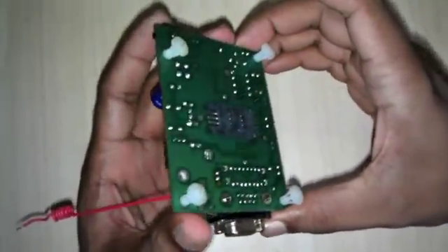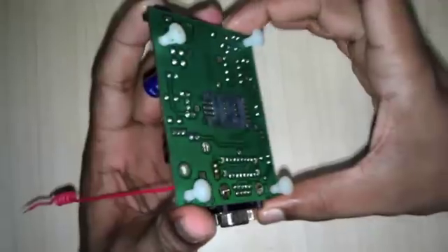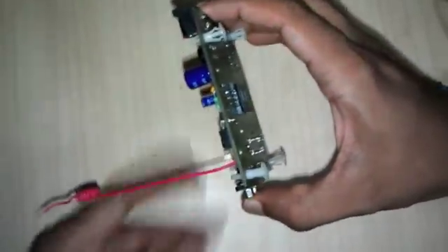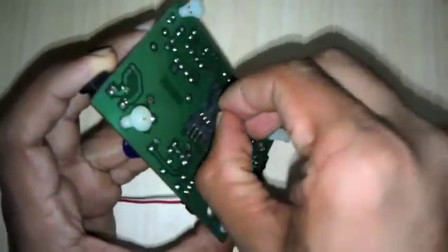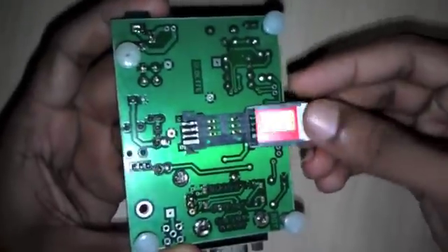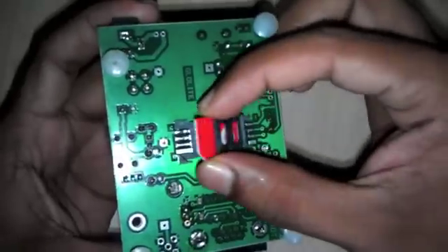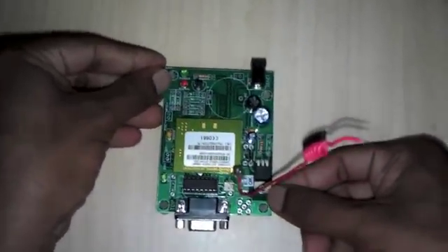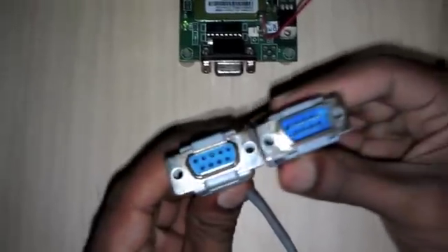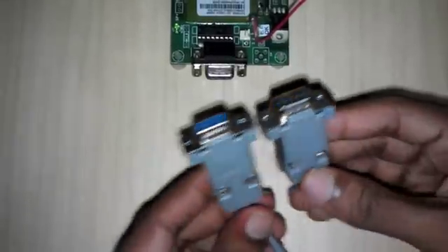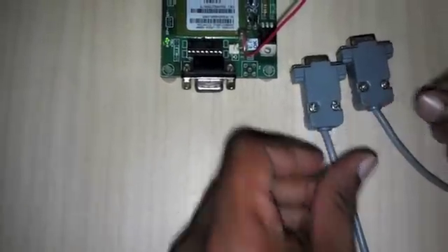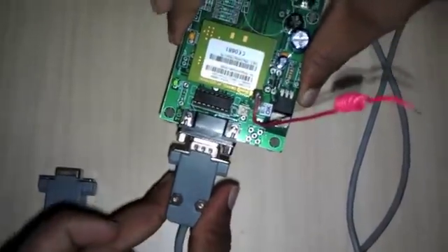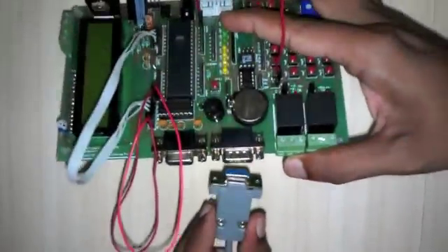This is a demo modem and not part of the kit. Your GSM modem might look different. In our modem, you open up the bottom SIM card flap and slowly slide your SIM card into it. Now close the flap and lock it. You will then need to connect the modem to the microcontroller using a serial cable, which is also provided in the kit. Let's see how this is done. This is how the 2 ends of a serial cable will look like. One end goes to the modem, and the other to the board, like this.